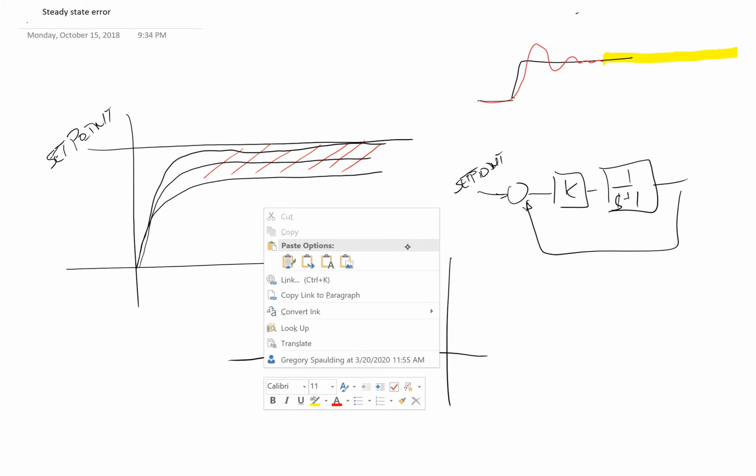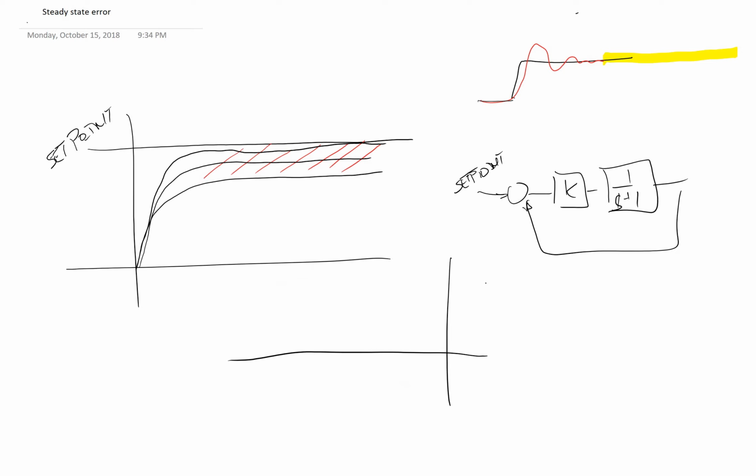And second of all, if we look at the root locus on this, we're going to run this out along the negative real axis, and what we're going to run into is the possibility of running into some high frequency stuff out here that's going to set off some oscillations or even potentially cause this system to go unstable. And so just cranking the gain up is probably not a really good solution.